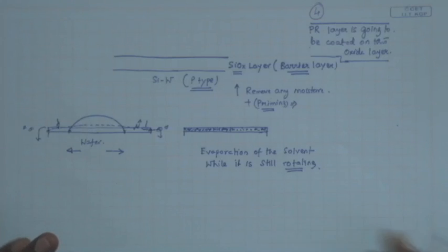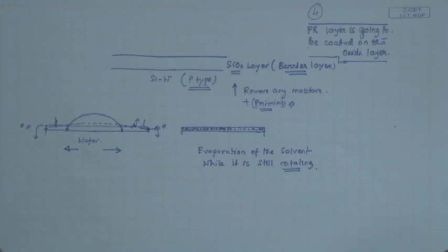So, irrespective of the wettability of the substrate, the solute covers the substrate uniformly. That is one of the real marvelous things of spin coating. Of course, under appropriate condition you can achieve two more things. You can get extraordinarily smooth films by spin coating on a smooth surface. Spin coating on a non-smooth or a rough surface or a non-homogeneous surface or a pattern surface itself is a matter of big research, and I intend to spend some time on that towards the end of this particular course when you are more mature to grasp the advanced issues.